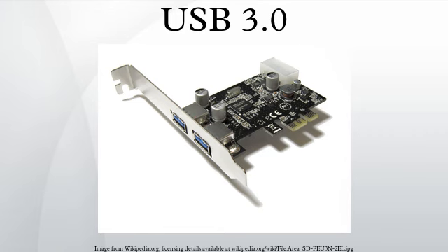Connectors. A USB 3.0 standard A receptacle accepts either a USB 3.0 standard A plug or a USB 2.0 standard A plug. Conversely, it is possible to plug a USB 3.0 standard A plug into a USB 2.0 standard A receptacle. A similar principle of backwards compatibility applies to connecting a USB 2.0 standard A plug into a USB 3.0 standard A receptacle. The standard A is used for connecting to a computer port, at the host side.